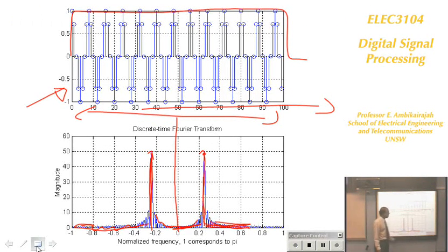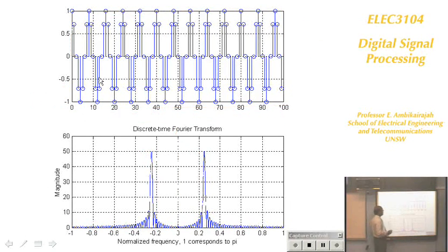You will probably come across this again later on in filter design. But for the moment, you need to know how to use that formula. So instead of x[n], you put cos n theta, and once you've done that, evaluate the summation or use the transform to get your discrete time Fourier transform. Discrete time is only the time signal. The Fourier transform is continuous here, like you've got values for every frequency point.